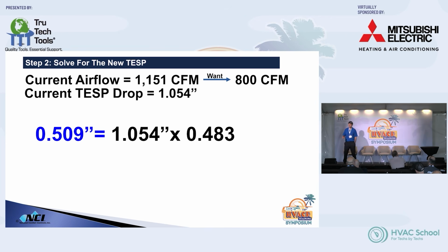So how often do you find a variable speed furnace not set up and it's just maxed out on high speed airflow, right? So if you have a 3-ton drive installed in a system that is a 2-ton, your static pressure is off the rails. And then you dial it in, and then all of a sudden, it's not so bad anymore, right? Look at how far it swings in the opposite direction.